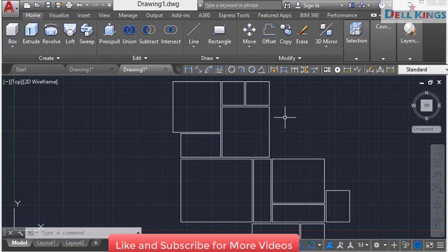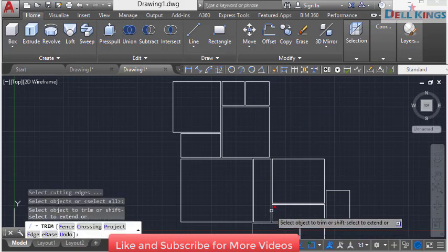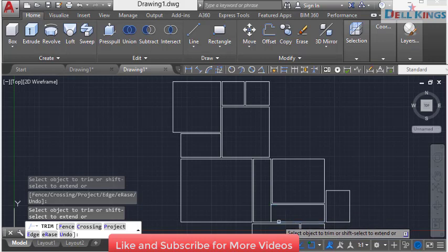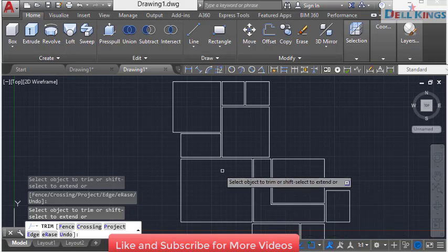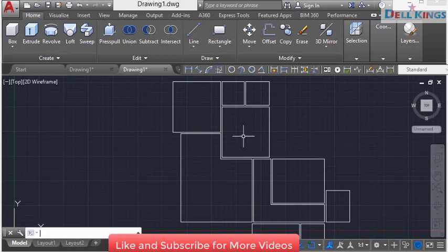So now we are going to trim some of these lines. So select trim from here and press enter, trim this and hold shift, extend this and trim this line. Now trim this line, hold shift, extend this and extend this line. You can now trim this line and then press enter.